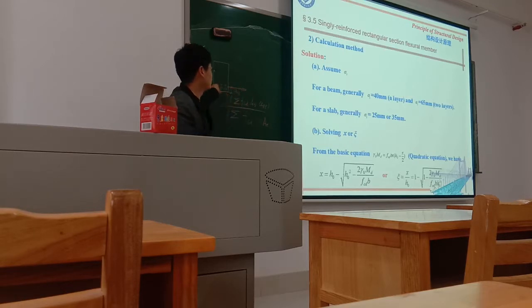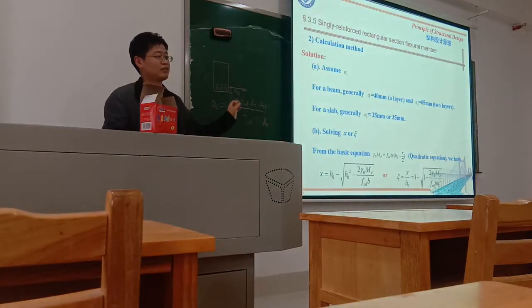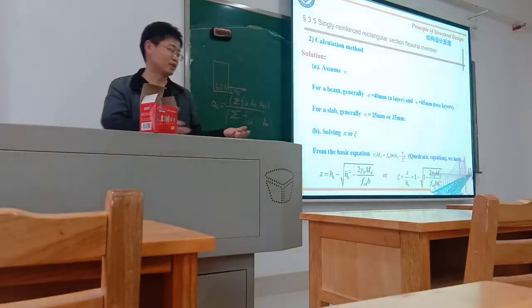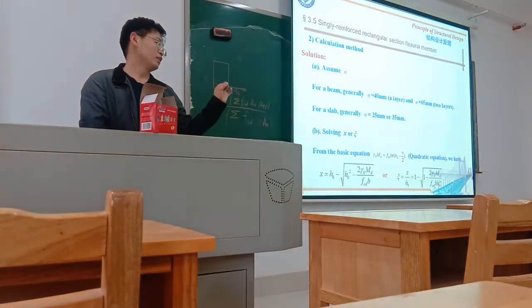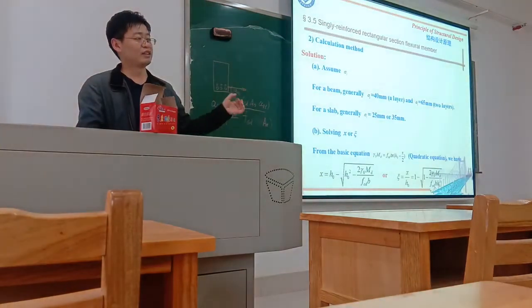Because if you use different types, maybe this is HRB 335 and this HRB 400, it's easy to make a mistake, especially on the construction side. For the worker, it's quite easy to make a mistake because you just see the outer surface of the reinforcement. It's very difficult to know which one is which. Only the diameter, maybe the smaller or the larger, is easy to tell.